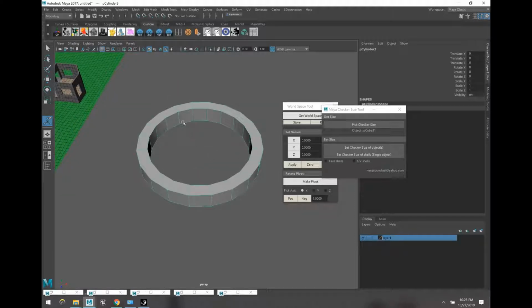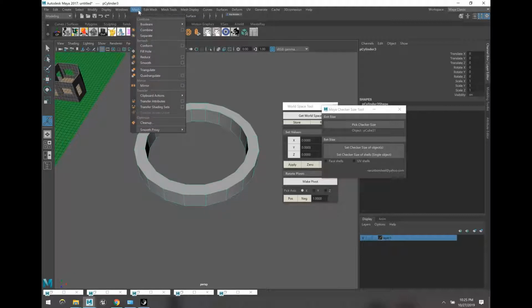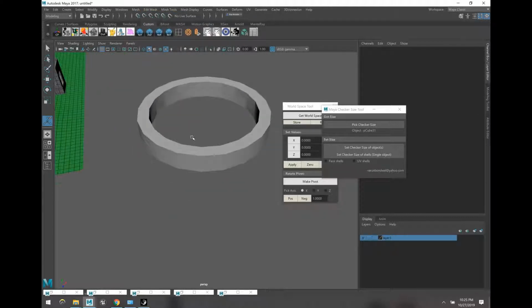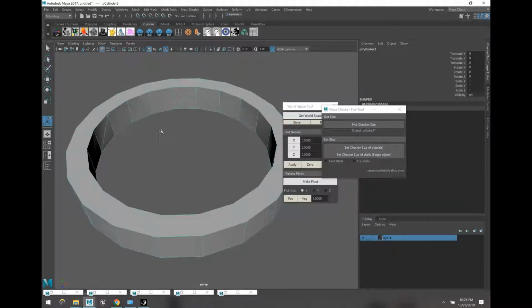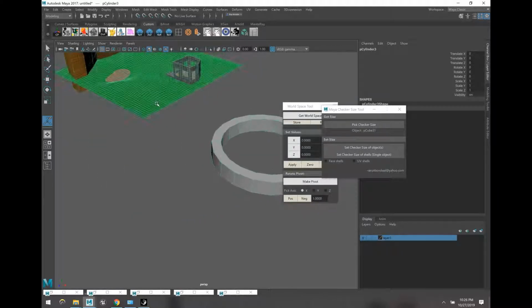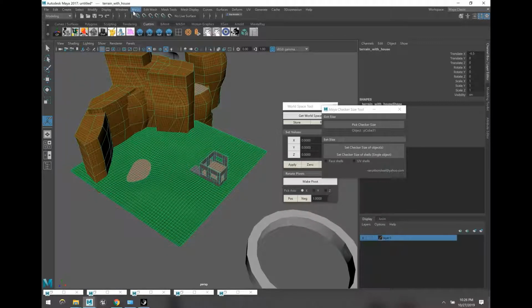Sometimes Unreal gets kind of confused with this, so you can do mesh triangulate, and I'll clean it. It'll run an auto triangulate. You could be like, oh, undo that, let's go quad. But you could see because of the ring, it couldn't fully recover it. At any point, if I want this mesh back, I can do a separate.